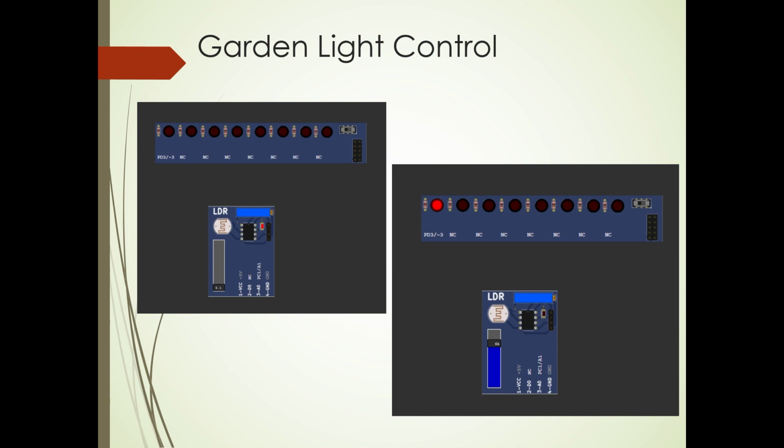The LED is encapsulated with a transparent cover so that emitted light can come out. The LED symbol is a standard symbol for a diode with the addition of two small arrows denoting the emission of light. The simple LED circuit consists of an LED, a voltage supply and a resistor to regulate the current and voltage.